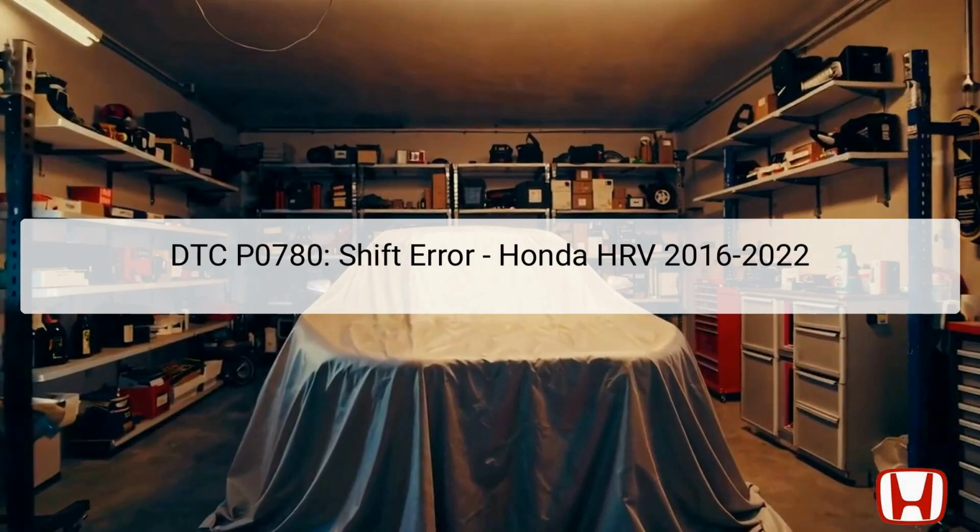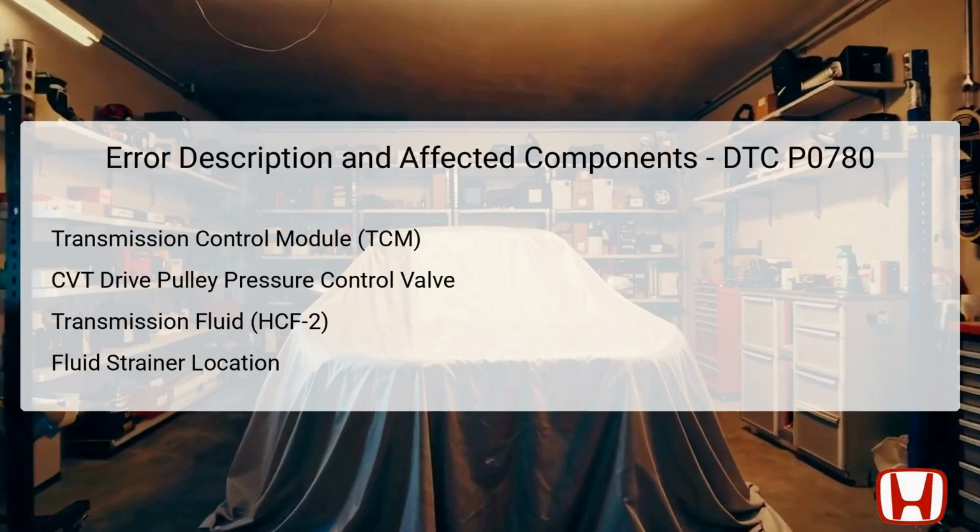The shift error indicated by DTC P0780 involves several critical components, primarily the transmission control module, TCM, and two specific CVT pressure control valves, one for the drive pulley and one for the driven pulley.